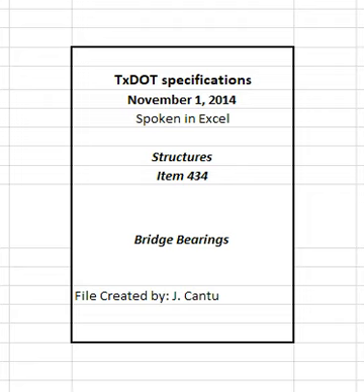3.1.5 Field Methods. Provide concrete surfaces for bearing areas under plain and laminated elastomeric bearings in accordance with Section 420.4.9, Treatment and Finishing of Horizontal Surfaces. Do not damage the elastomer when welding near bearings. Damaged bearings will be subject to rejection and require replacement as directed.